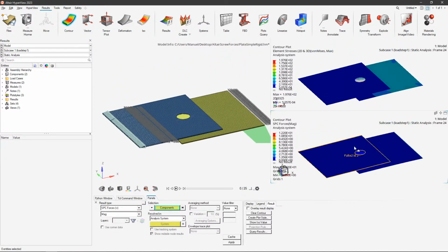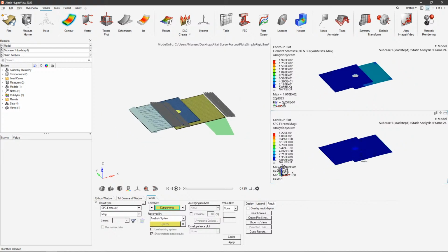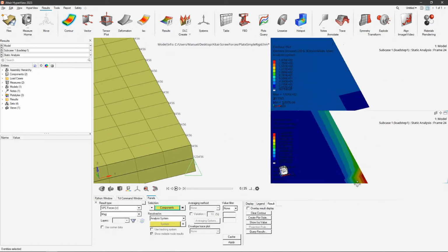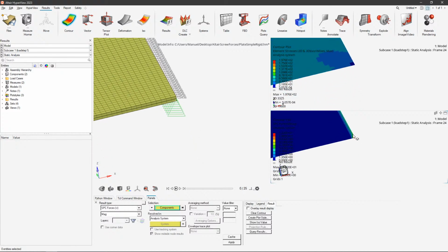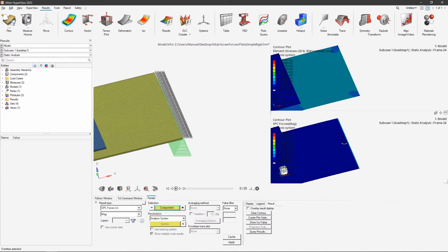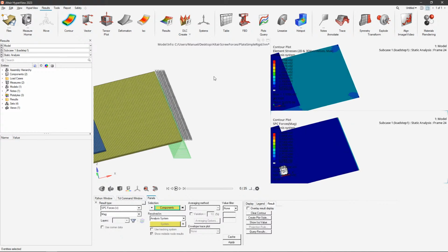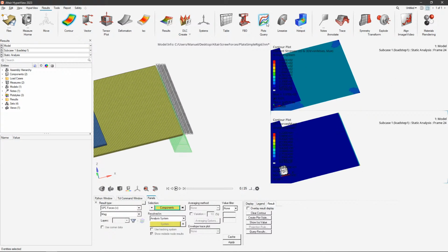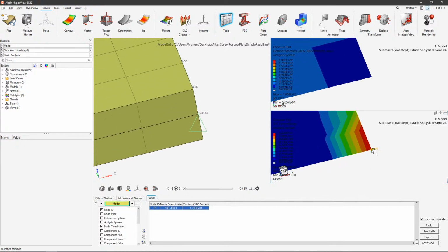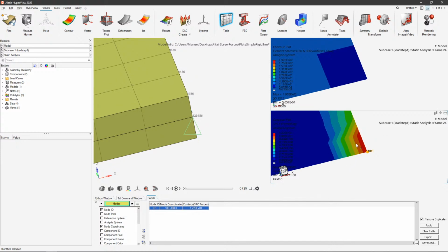And you can see that you have 122. Yeah, it should be at one edge, right? So this is here. But again, in order to have the whole thing, you would have to sum it up, right? So at least that's my understanding. So you could go to a table, put in those nodes and see, okay, the SPC force here is 120 newtons.